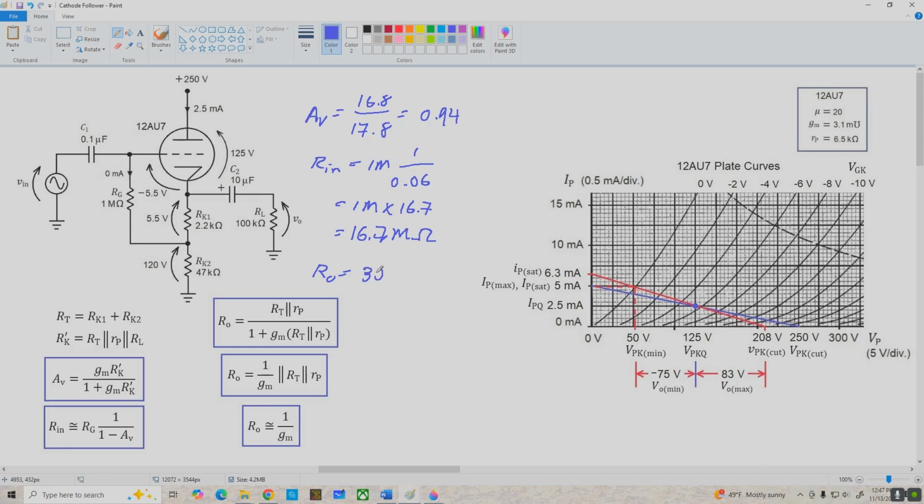About 305 ohms either way. All right, so we have a fairly low output resistance, and although we're driving a pretty high resistance load this time, we could effectively drive a much smaller resistance because of this. Now, the approximation down here, 1 over gm, is not too bad in this case. If we calculate it using that one, we get a resistance of 323 ohms, which isn't bad.